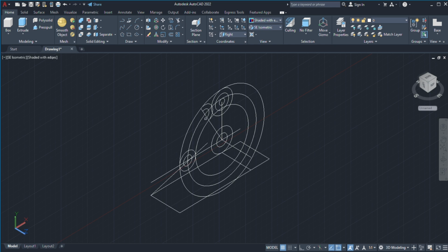You trim too much. Remember, we also want this circle to be tangent to this one, and these small circles here are a radius of 8, so we'll have to offset this one by 8 upwards and by 8 downwards. Offset by 8 and upwards.